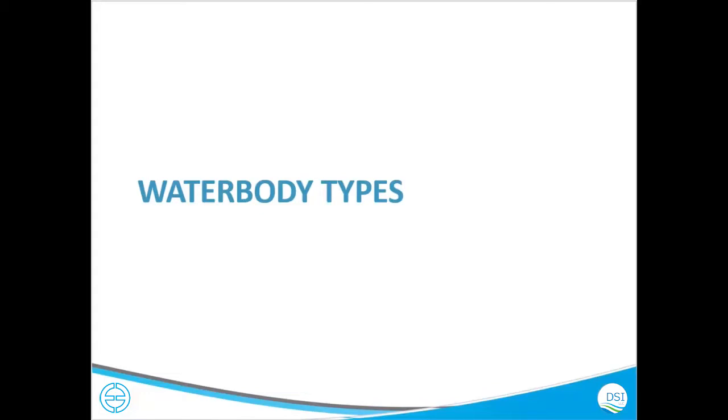So let's say you're working on the Gulf of Mexico, then you will find out which harmonic constituents are important, whether it's M2, N2, O1, K1. These are different components. One is diurnal, one is semi-diurnal. M2 and N2 are semi-diurnal. So you can do harmonic analysis of your time series and see what the dominant harmonic constituents are. Or you can always go to NOAA, and it gives all the harmonic constituents for your site.